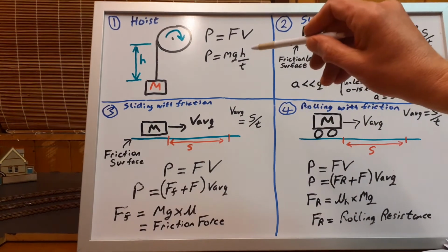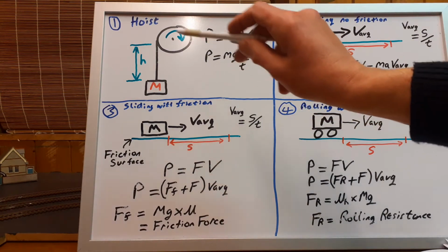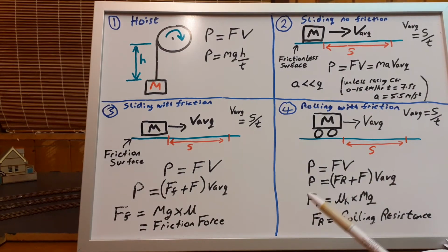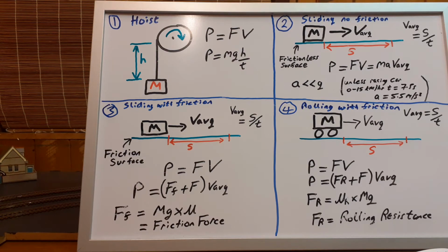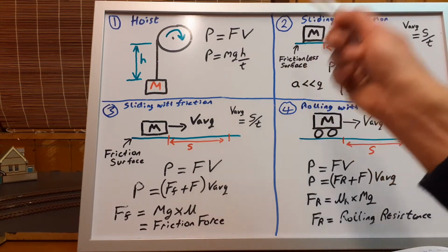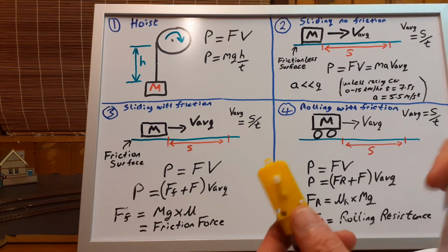So my advice is work out what the wattage required to lift the mass at that velocity, and you've got the maximum power you're ever going to need for your motor. Okay, so you've calculated your wattage based on this worst case scenario. So you get a number, okay? So you're looking to find a motor to do that. And this is where the problems arise.